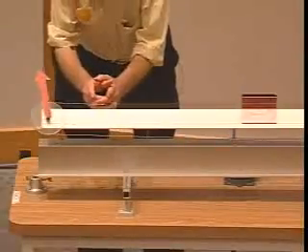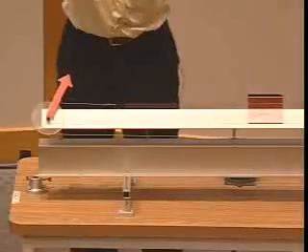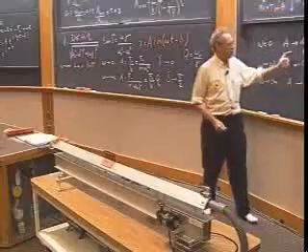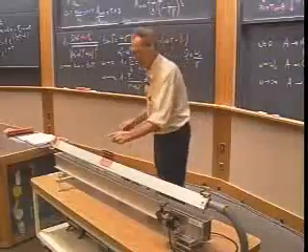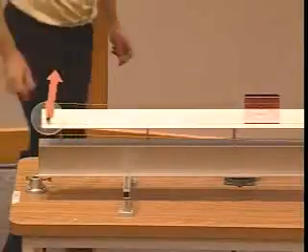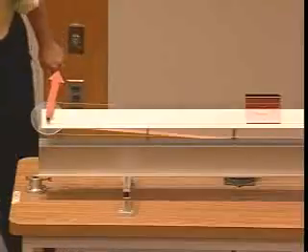Now, this was the amplitude, twice the amplitude of the driver, and when you look carefully here, it's less. It is that eta 0 over 2 that this gentleman immediately noticed, because we have two springs. So you see here, apart from the factor of 2, you see the delta 0, and you see that the amplitude, indeed, is half of the amplitude of the driver because of the two springs. Now we're going to resonance, omega 0, and now nasty things may happen.